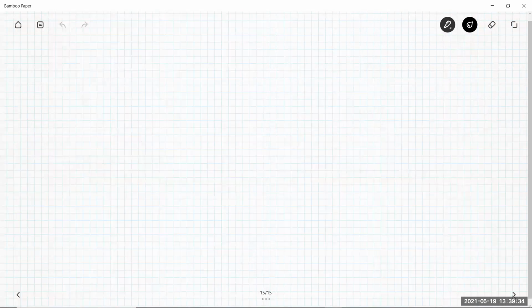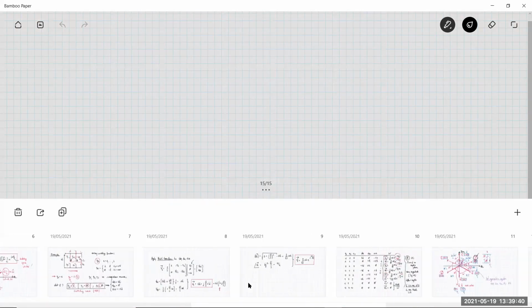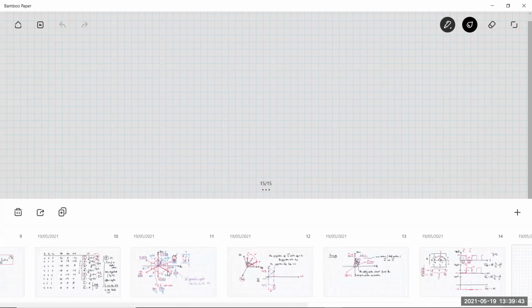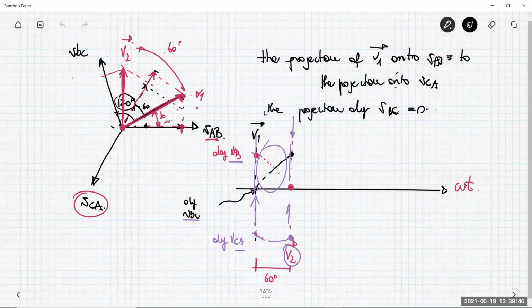Let me put this value on my previous plot. Where are they? Here, on the line-to-line voltages evolution. Remember, I have V1 here and I have V2 here, which represent something in discrete positions. Now I use the average value obtained by continuously changing between V1 and V2 to synthesize something which is in between these two discrete values. And I get something which is VAB, similar and equal to VBC.